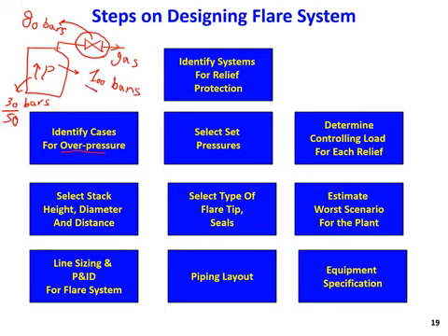So we set this safety valve at 80 bars, which is far below the 100 bars, and above the normal operating condition. If the pressure reaches 80 bars, the valve comes into action, opens the line, and purges the gas that usually goes to the flare. So this is the definition of the set pressure in this case.